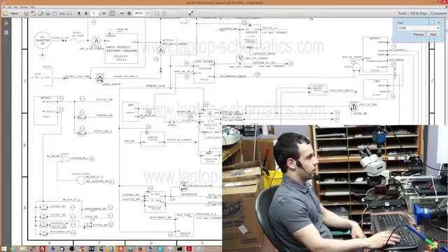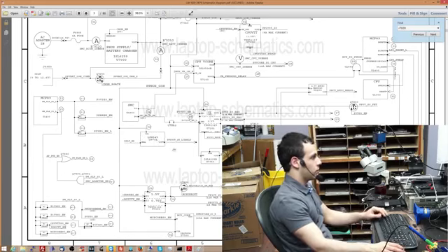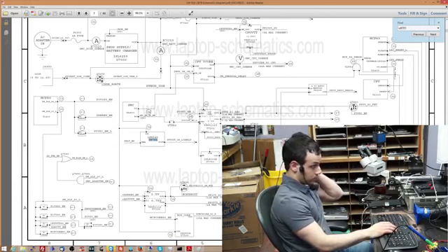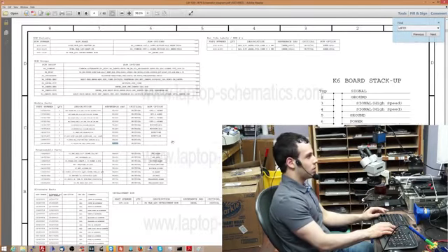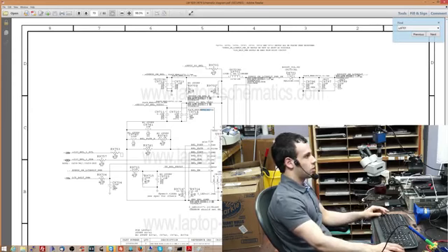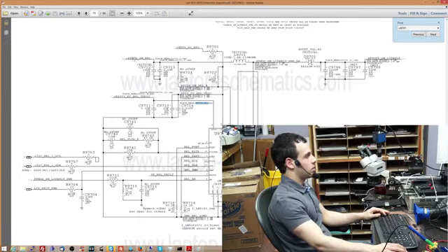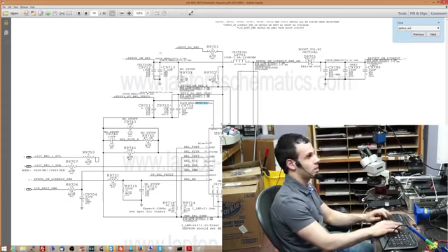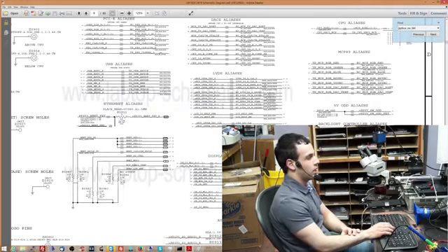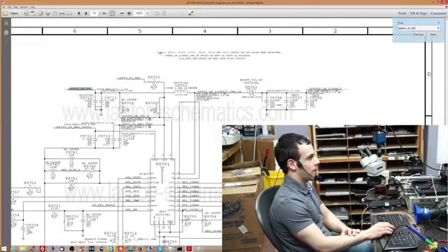Let's say you're having an issue with the backlight. You go over to LP8545 because it says backlight over here. So U9701. And there really is no how-do-you-read-this. It's just a document that's filled with interconnected electronic components. So here is the chip. What do you see here? You see ppbus_SW_BKL. You may be wondering, what the fuck is that? The first time I saw that, I thought the same thing, which is why I hit Control F in my PDF reader and hit Enter until I found something that made sense.